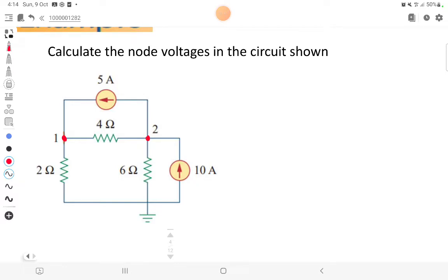So now after that, we would create our assumptions of the direction of current. Let's say this will be my I12 coming from V1 going to 2. This will be my I10, and this will be my I20, or from V1 to 0, or to the reference node, and V2 to the reference node. Now after that we can create our equation.